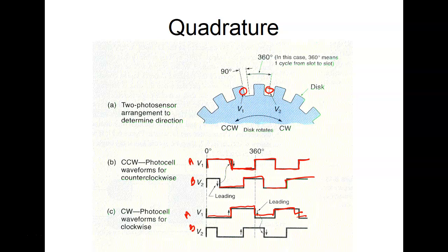And we do have some of these here. We don't have enough for everybody to do a lab on. In fact, we have to teach our oscilloscope if you haven't had AC. So you can actually see this. Now this right here doesn't actually mean anything until we do what? Until we run this through a counter. So what we have to do is count it. The resolution of incremental encoders is set by how far your counter can count.